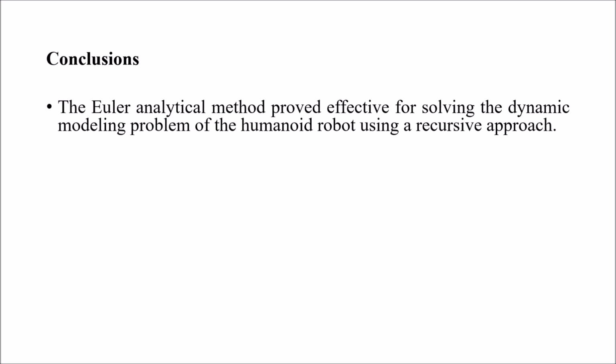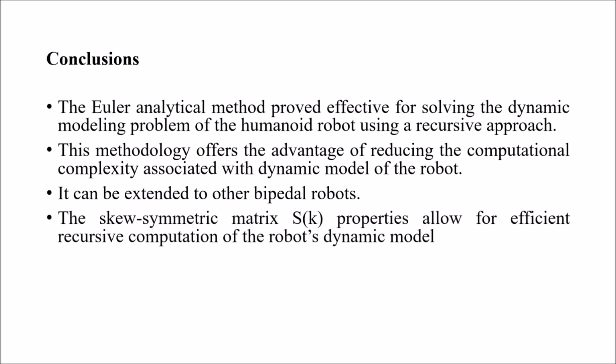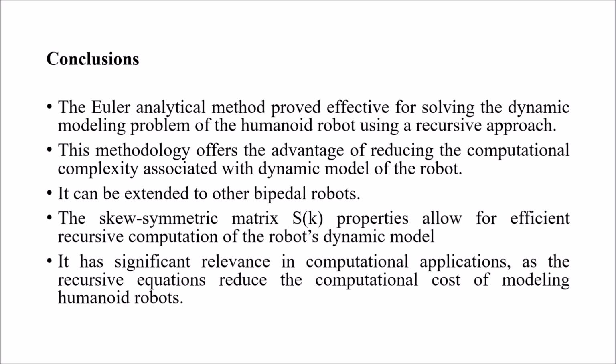The conclusions are: the Euler analytical method proved effective for solving the dynamic modeling problem of humanoid robot using a recursive approach. This methodology offers the advantage of reducing the computational complexity associated with dynamic model of the robot. It can be extended to other bipedal robots. The skew-symmetric matrix properties allow for efficient recursive computation of the robot's dynamic model. It has significant relevance in computational applications, as the recursive equation reduces the computational cost of modeling humanoid robots.